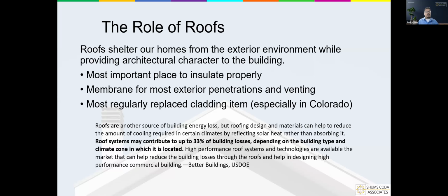But a third of the money that you spend warming things in your furnace, in order to warm your home, to see that being such a contributory force towards the losses and the dollars spent heating a home makes it a prime target for improvement. And we've seen that through different code cycles. Through the 18 we saw a crest in total insulation value being attributed to the roof in the 21, and then in the 24 code we're going to look at how it's gone back to a bit less insulation because of some concerns on payback and things like that. But ultimately, it's pretty clear that it's been targeted as a very important part of the discussion when it comes to energy efficiency and the design of the thermal envelope.